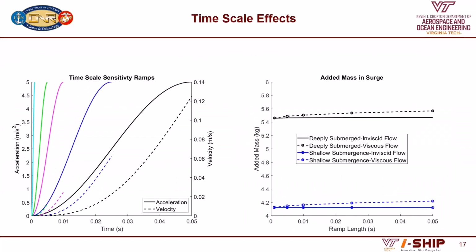And then I'll actually go back. And so if we move backwards in smaller and smaller time steps, the inviscid and viscous cases actually converge on one another. So viscous effects aren't actually all that important at such small time scales. This will lead into some future studies when we're running from steady state with an already formed boundary layer.